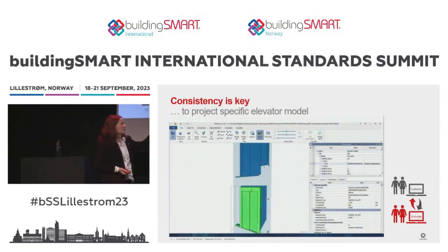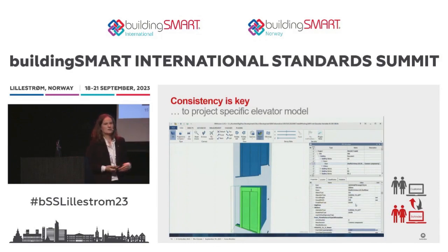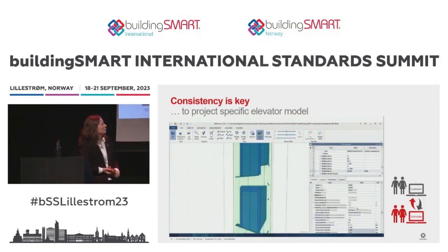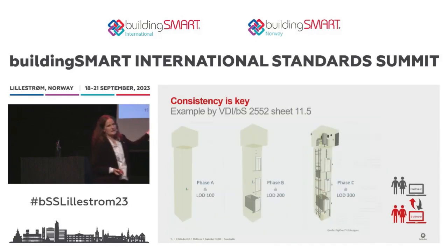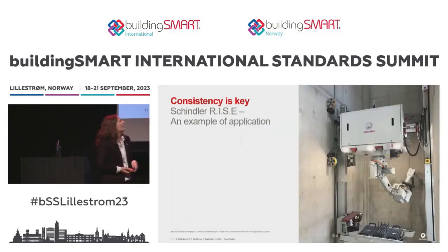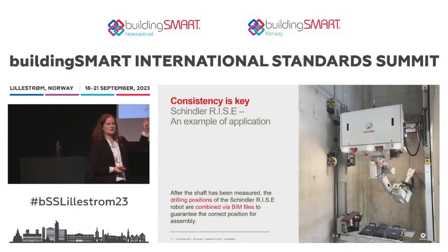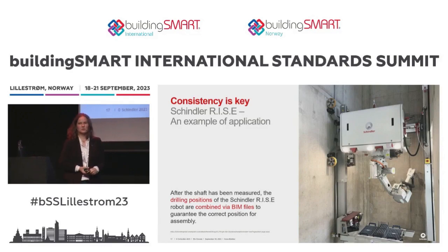And of course, we have also used here, for example, the IFC door entity, not just the elevator, depending on the model requirements. And for different phases, I think we have different information needs, so we have also defined different LODs. And we use, for example, internally the data also for the installation robot in high-rise buildings to drill the holes for the car railing.